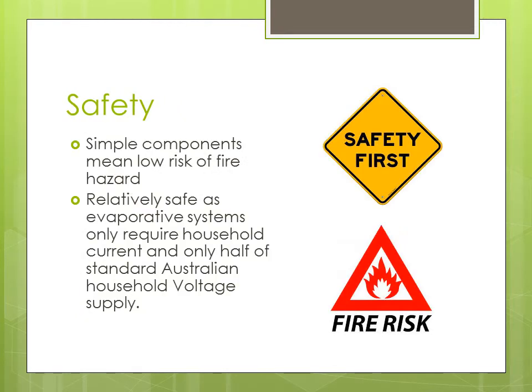Safety. The system's simple components of a pump and a fan make fire hazards almost non-existent, especially because it is a cooling system. There have been a few occasions where too much moisture from the system has been distributed to exposed electrical wires, causing a fire hazard, so consideration of such a hazard in the cooling zone is important. Because the system runs off common house current and operates with just 120 volts of electricity, the potential chances of fatal electric shocks in faulty systems is significantly decreased compared to other air conditioning systems.